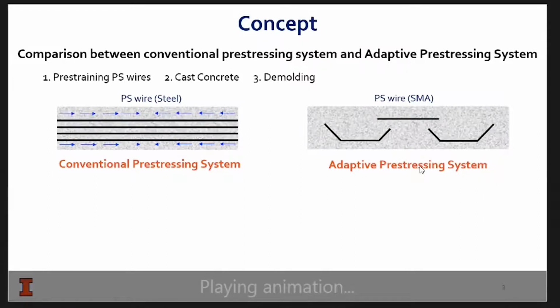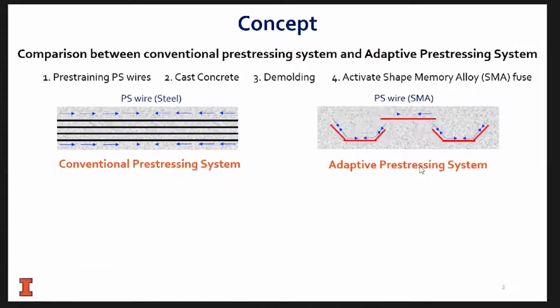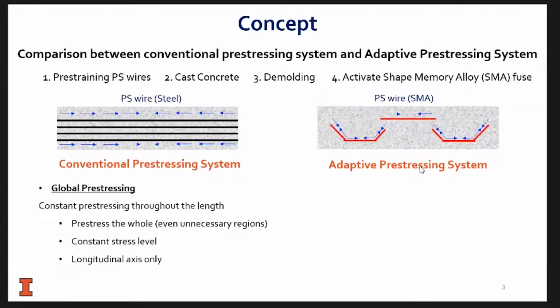Now, the one on the left is looking at the pre-stressing globally, meaning the level of eccentricity that Riley was talking about. Pre-stressing is nothing more than just P times E, force times eccentricity, right? With this design on the left, we have very, very little room to play with for eccentricity. And I'm going to talk about that later.